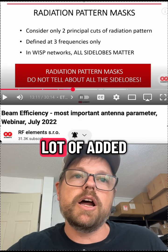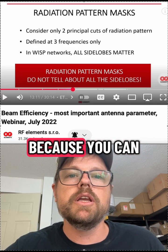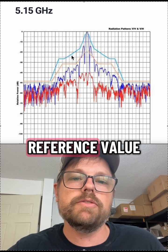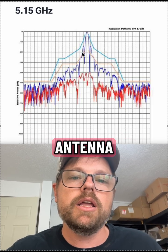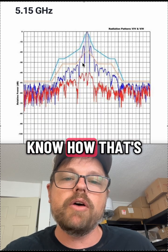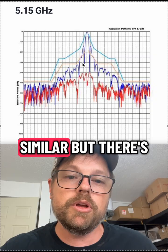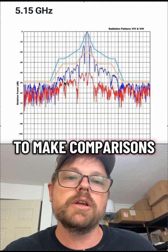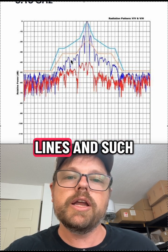So it brings a lot of added value in terms of noise suppression in WISP networks because you can use it as a reference. So the ETSI mask is a reference value. It lets you know what you should expect from an antenna. Otherwise, it's pretty difficult to read an antenna pattern just on its own, know how that's going to compare to another vendor's antenna pattern that looks very similar, but there's small details, and it's hard to make comparisons if it's operating at different frequency points, has different grid lines and such.